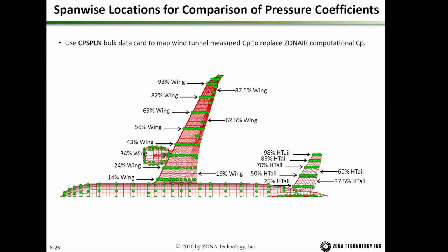So we do it on a component by component basis. First, we use a 3D spline to spline the pressure on the fuselage, then also the engine nacelle using 3D spline TPS, and for the wing leading edge, we use the thin plate spline method, and for the rest of the points on the wing, we use the IPS method.